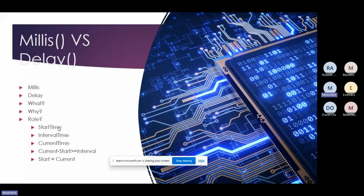Then you perform arithmetic in order to check the condition. What is the condition? The current time, the time of the microcontroller at that moment, minus your start time, is it greater than or equal to your interval?